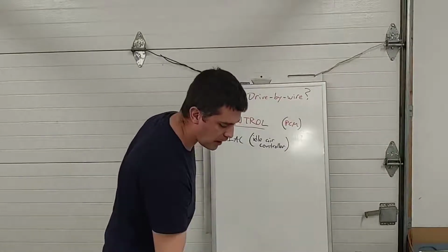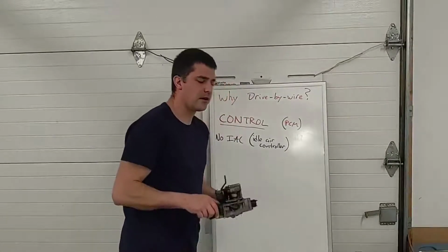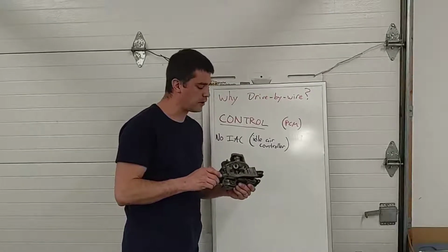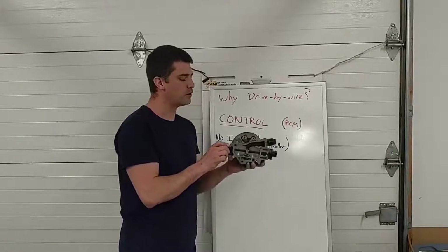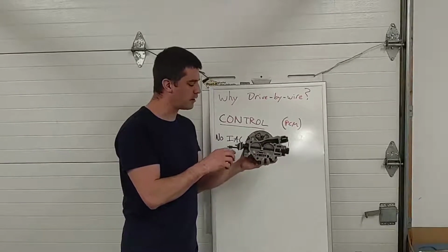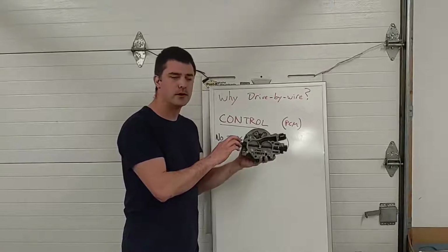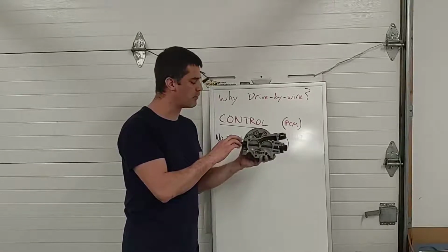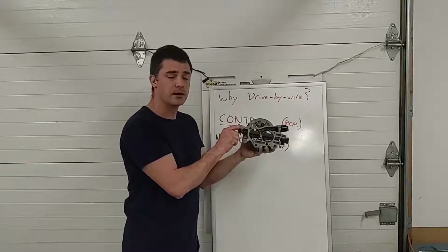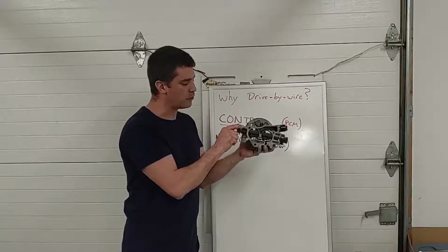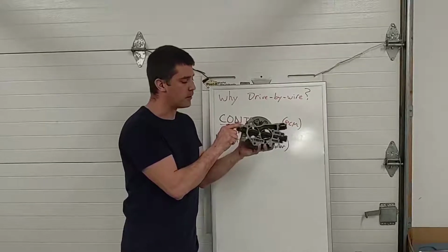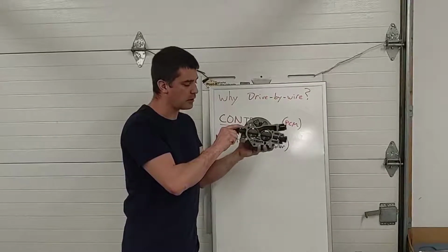Likewise, you may have been driving on the highway once and thought, I don't want to keep stepping on this pedal. I've got another hour on this highway to go, and you set something called cruise control. In the olden days, cruise control was accomplished by a separate actuator. There had to be another piece on the car under the hood, either a vacuum-operated device or an electric motor-operated device that would hold this throttle at your set point, and then looking at the vehicle speed sensor, as you slow down because you hit a hill, open the throttle a little for you, or if you start to speed up because you're going down a hill, close the throttle a little for you.